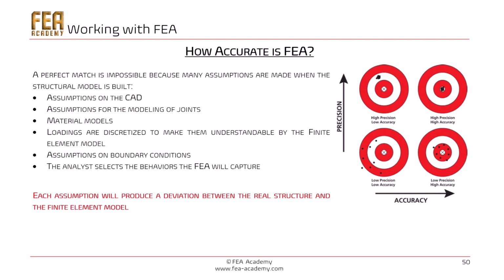FEA can yield spectacularly accurate results when compared with physical test results. However, in a complex FEA, it is still not possible to obtain an error of less than 1% in the whole model. Okay? Generally, a target of plus minus 10% global error permits to obtain very good predictions. But this target does not prevent the occurrence of errors of less than 5% in some local regions of the FEA.